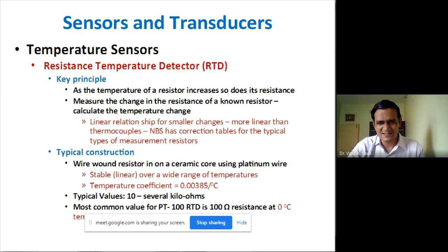You can utilize this RTD for measurement of temperature. In this RTD, you have a certain resistance made of platinum, copper, etc. And as and when you heat one end of this metal, it will generate a change in resistance. You can measure that change in resistance by applying this in one arm of a Wheatstone bridge circuit, and then you can measure the effective temperature.